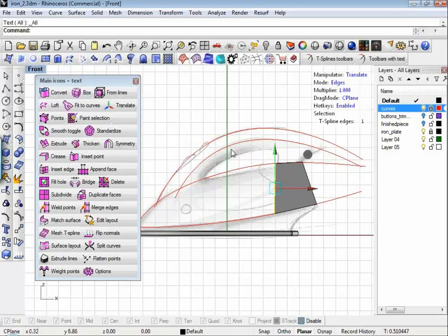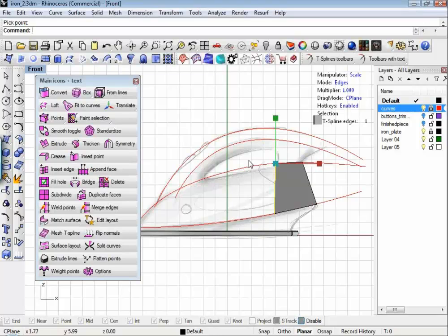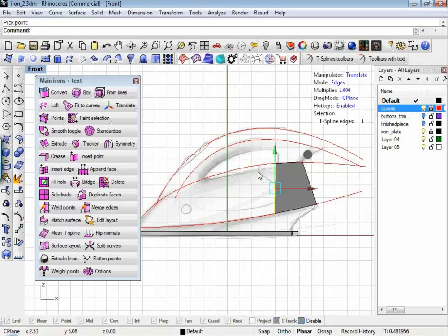The W tool makes for translating, for moving things. The E key brings up the rotator. The R key brings up the scale. And the T key allows you to snap the manipulator to a different location. So that's kind of the basics of how the heads-up display works, and this concept of being able to flip through the manipulators really quick with hotkeys is really nice because it allows us to do all of this with just a handful of tools.